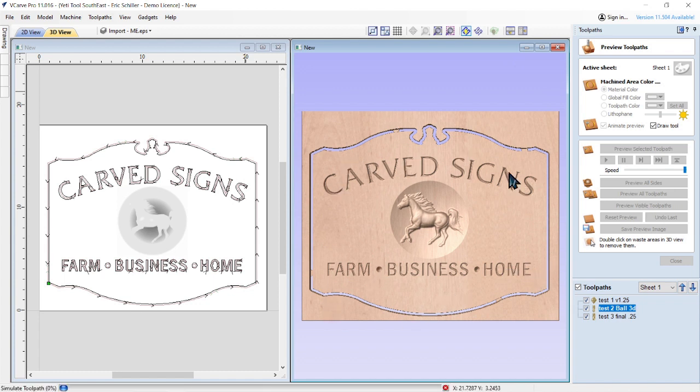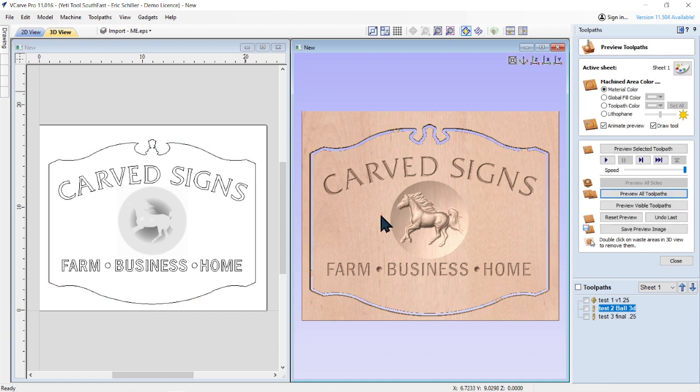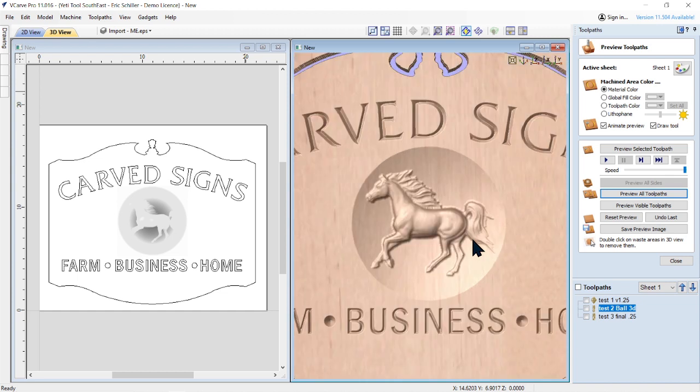So he's engraving just with a V-bit and then doing a ball nose here to do the 3D and then the cutout. He's got tabs. So everything looks good, except he says he's getting flat spots on the 3D engraving. So what that means is the 3D object is up too high in the design. And there's a way to quickly check this.